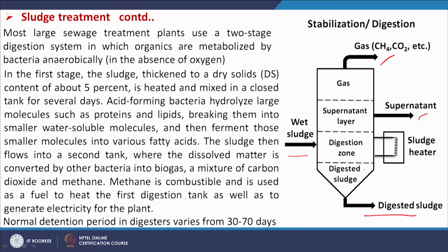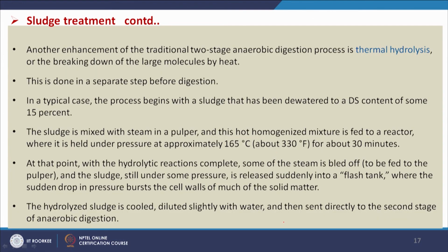And the aerobic process is also used, and some lagoons are also used. In the case of the anaerobic process, the normal detention period in the digester varies from 30 to 70 days. Another advancement of this anaerobic process is the use of thermal hydrolysis.